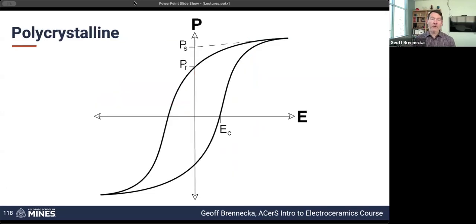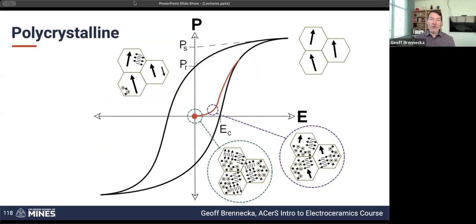Okay, so as a reminder, we're applying an electric field to these ferroelectric materials, getting all the domains to line up, and then taking advantage of that for the piezo applications. So last time we ended with talking about how quickly this happens. So we have a nucleation and growth sort of process where we apply field, and the domains that are oriented along the direction of that field grow at the expense of the domains that are oriented in a different direction. And so we talked about the impact of that on the kinetics. So the energy that's involved is part of it, and then the way that the domain walls are moving is another part that determines how quickly this happens.